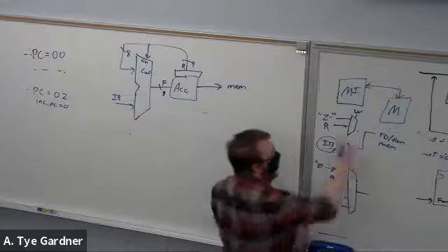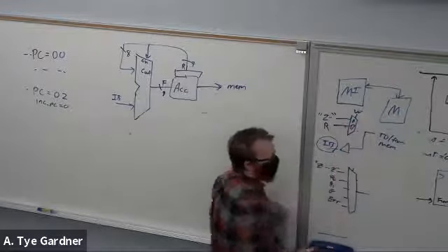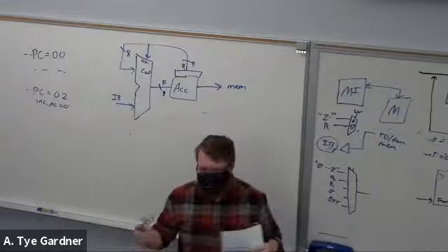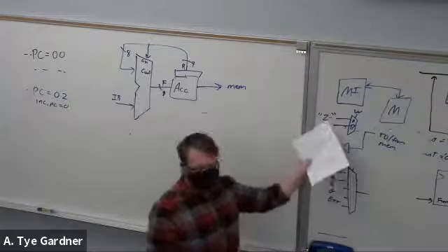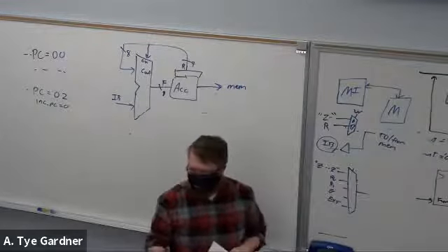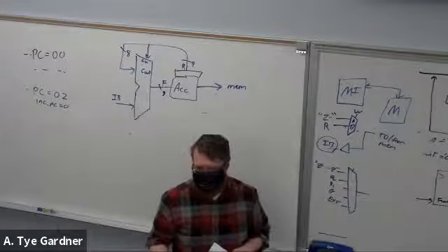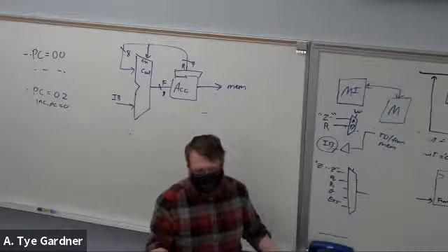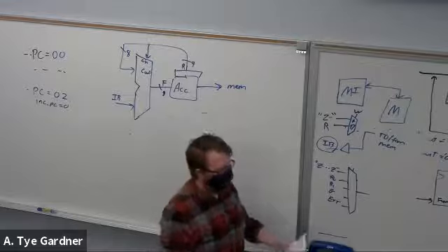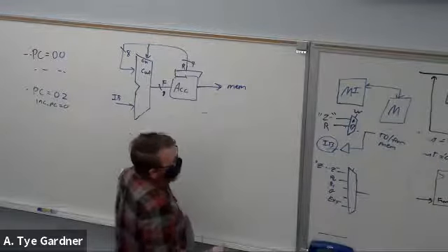And their ports are like A and B. Don't go make a new mux. Just take the code that you've already written and do the port mapping of Z and R into it, right? This is something we want to remember: we can reuse this code. We don't have to write a new mux every time. We can just use what we've already done.